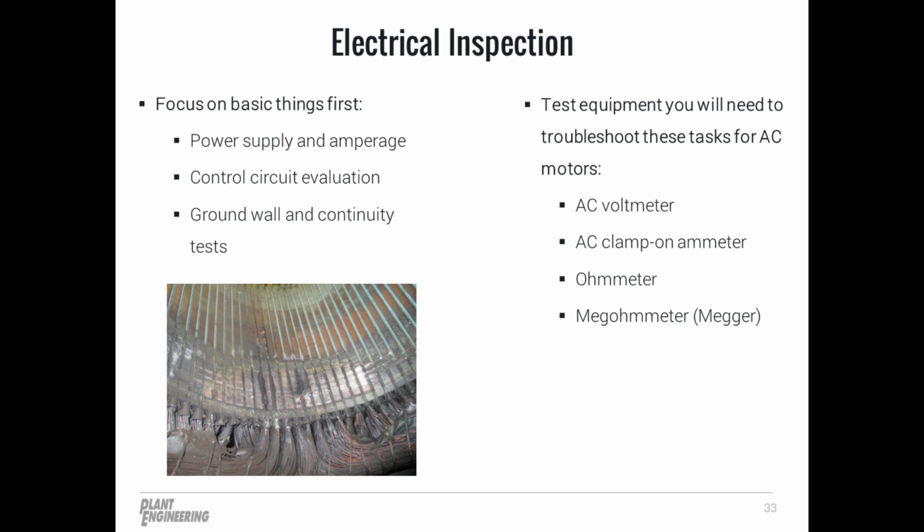By using a voltmeter, we will first check for applied line voltage at the power supply of the motor at each line to ground to eliminate any potential blown fuses, and then we can proceed to test each phase line to line. The applied voltage could be direct wired from a simple on-off switch, or it could be coming from somewhere a little more complex, such as a VFD or a soft starter. When performing these tests from a control circuit, such as a VFD, we will want to make sure that the power is available at the incoming and outgoing side of the unit when in run mode.